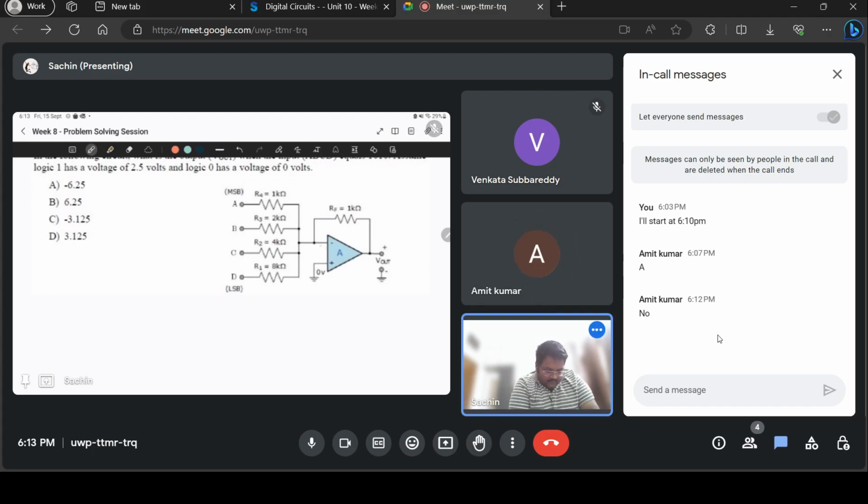Okay. So when the output is connected back to the negative input terminal, it's called negative feedback. And when you connect negative feedback, what this operational amplifier will do is try to bring this voltage down to the same as the voltage at the positive terminal.